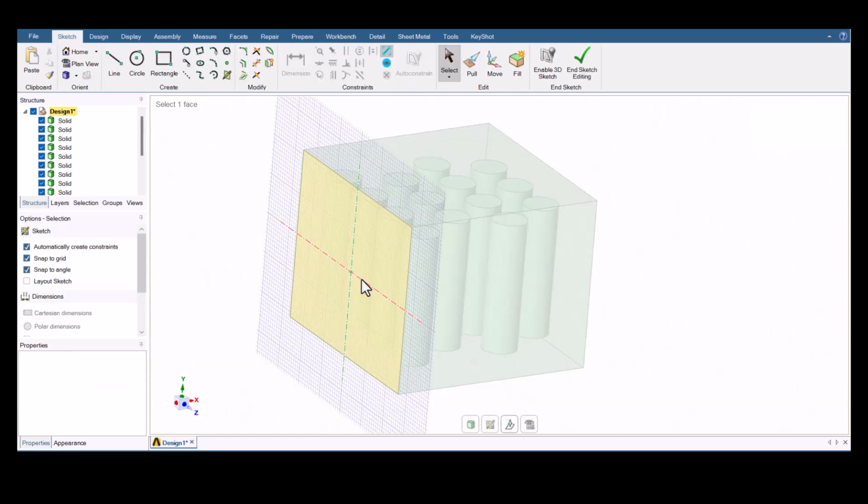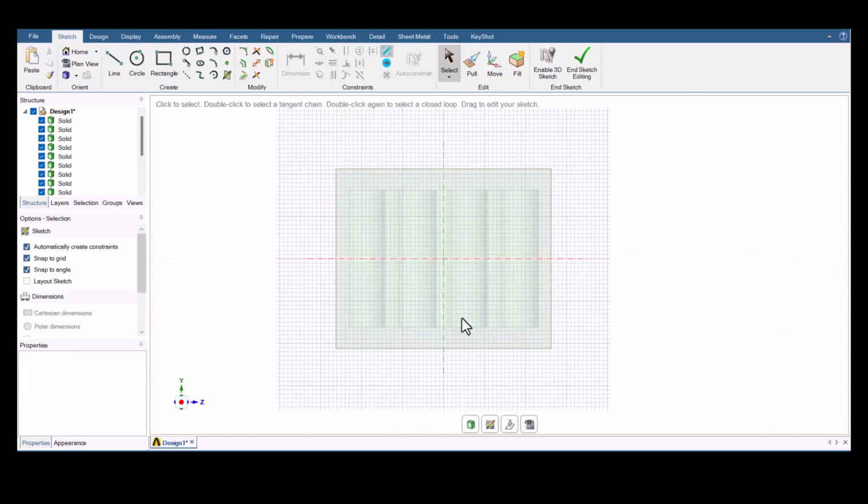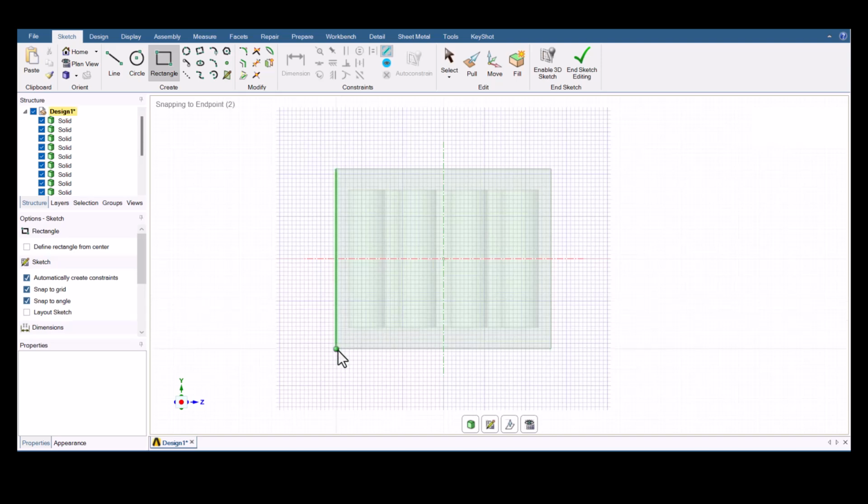Create an inlet on the left surface from where we want the cold air to come inside the CFD domain. You can vary the inlet dimensions to study its effect on the results. Similarly, create the outlet on the opposite surface.